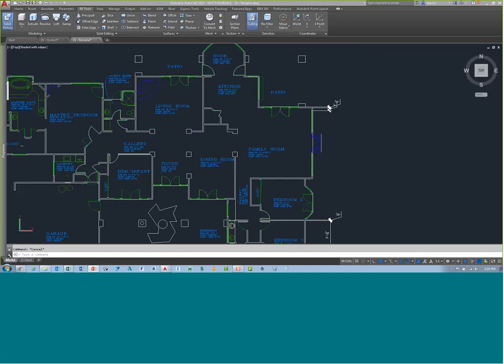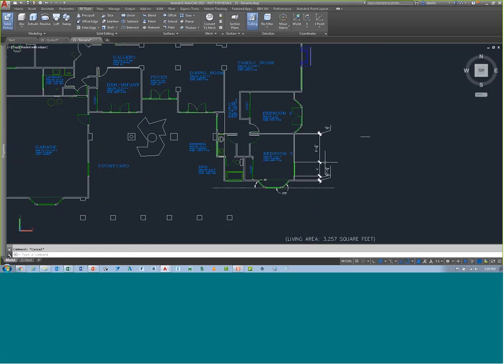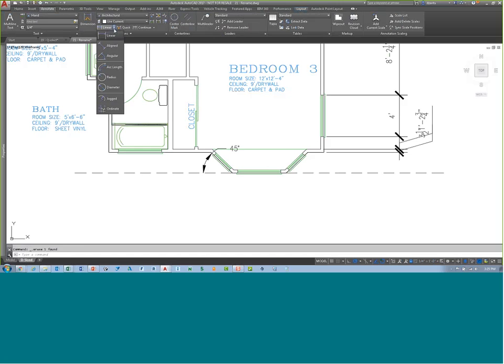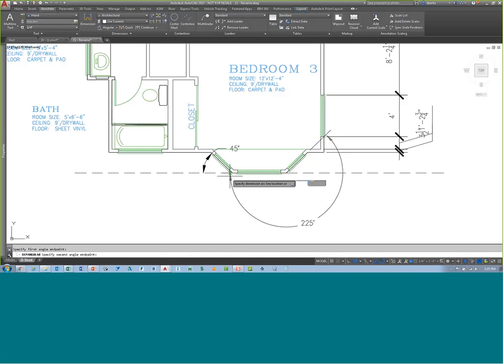It's 3:24. Okay, dimension angle is greater than 180 degrees, which is down here. So we'll switch over to D-size sheet. And in order to do this, we'll delete this one. We'll head over to annotate and do the angular dimension command. There is an option here called specify vertex. So if I just hit enter, it allows me to specify that vertex. So I'll pick that corner. I'll pick this and here to tell the software it's that line initially, going around this way to this point here for that line, and then I can click and place it.